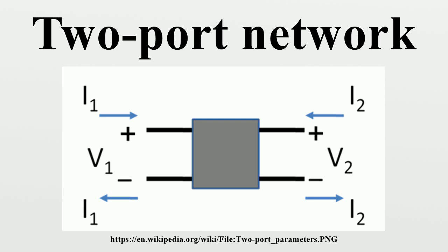Example: common base amplifier. Note: tabulated formulas in Table 3 make the G-equivalent circuit of the transistor from Figure 8 agree with its small-signal low-frequency hybrid pi model. In Figure 9, notation: R pi equals base resistance of transistor, Rho equals output resistance, and GM equals transconductance.